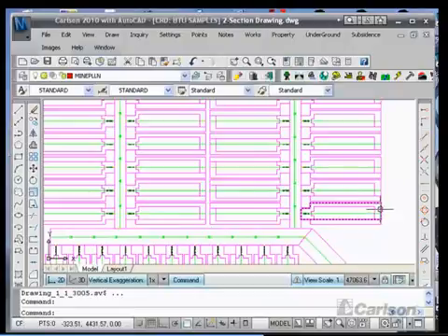This perimeter was used on each section for advanced mining with a separate extraction ratio from this panel, where we had a combination of driving rooms on the right hand side and then recovering pillars in the center of the panel. And in doing so, we would schedule this to drive up on that outline and back on this one, and did that for each panel.